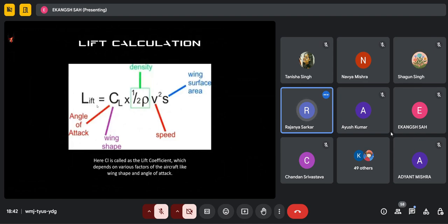next we have seen the formula for the lift, and it was defined as lift equal to half rho v square s CL, where S is the wing surface area or effective area of wing, V is the velocity of wind with respect to the aircraft, rho is the density of air near the aircraft, and CL is the coefficient of lift that depends upon alpha and some other complex parameters, right? And L is the lift. Moving on.